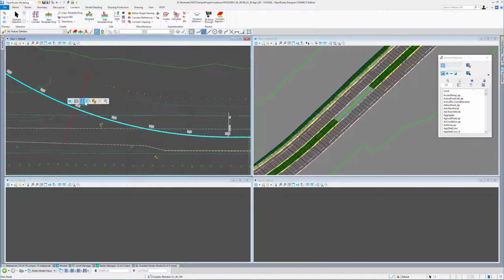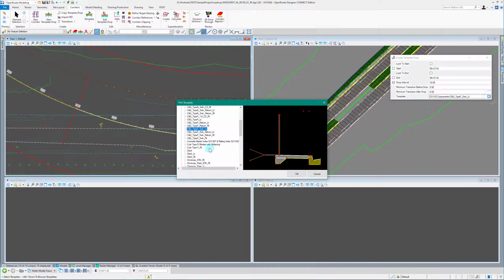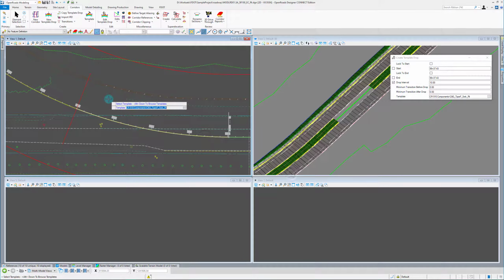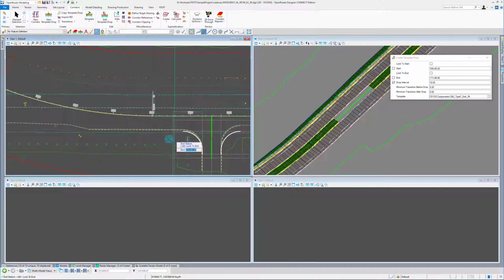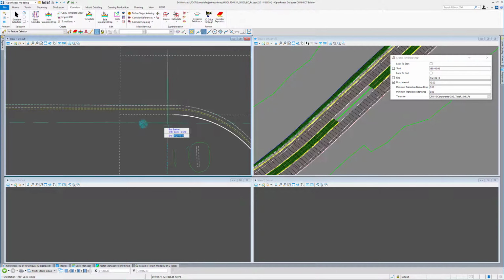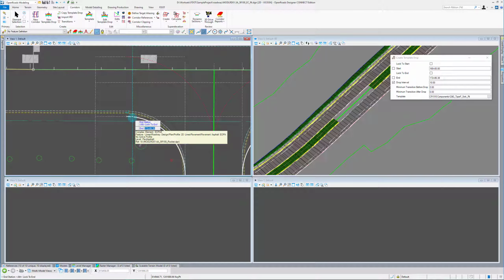Create our corridor here along our center line, EC right, and choose our template. So this time I'm going to snap to here. Well, I can snap, it doesn't matter what point you snap to, but we're on the right side, so we can snap to there. This time I want to stop and make a gap for my side street rocket here. So I'm going to snap to the PT of this and do my 10-foot drop interval.